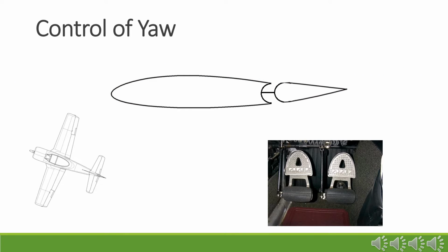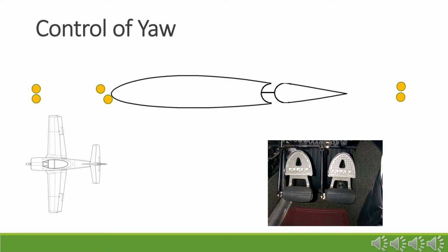By once again bringing both rudder pedals back to a side-by-side position, the normal and perpendicular forces are stopped while the drag force is minimized. The aircraft stops changing direction and remains on its new heading.